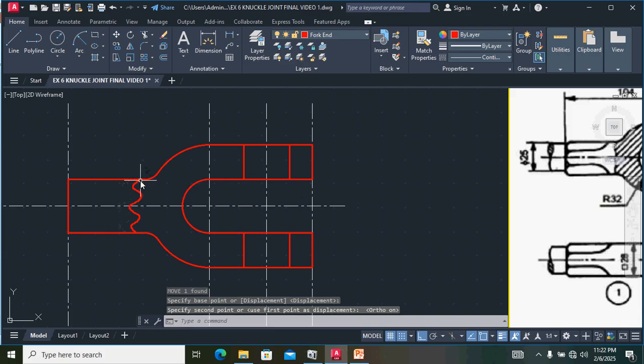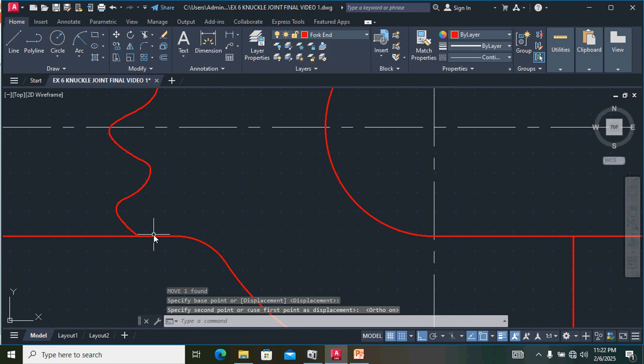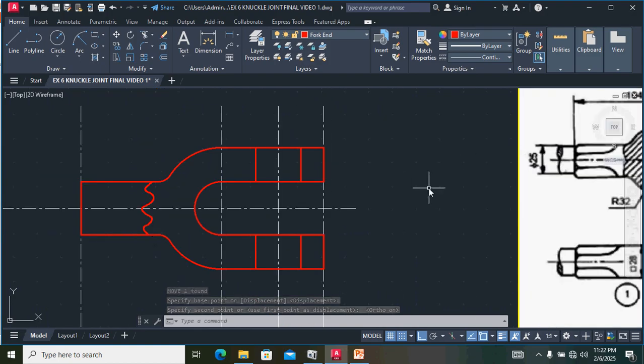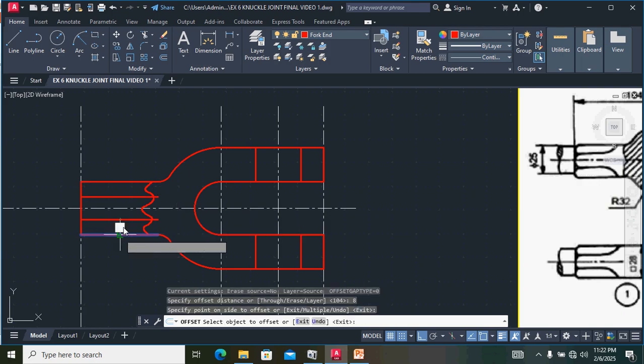In this case we have to click the line and click this point and this point, enter. Next again we go to line command. For reference this line, click here and click here and enter. Now we want to take fillet. Okay, in this case we have to fillet.